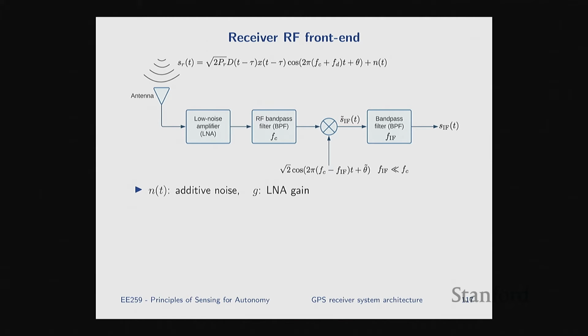So what happens here is we have a local oscillator that is generating this sine wave at the nominal carrier frequency, offset at what is called the intermediate frequency. So it's generating a cosine of 2 pi (fc minus f_IF) t, right? Why that? Why not just demodulate by fc? Why are we going to this intermediate frequency? It's an architecture decision. There's nothing wrong with demodulating right down to fc. But this idea, which is called the heterodyne architecture, is used a lot in communications.